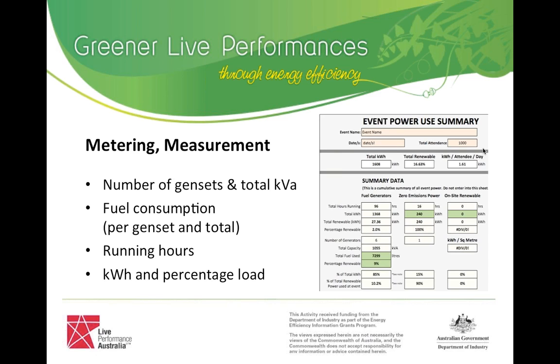Okay. So at the start, you there? Yes, hello? Yes. Yeah. At the start of an event, the kilowatt hour reading can be taken off the controllers on a number of machines. At the end of the event, the same can be, and you can work out your total kilowatt hours that way. We also have some logging functionality in the machines. We can actually log at set points in the machine. So every 5 minutes or every 15 minutes, we can actually see what loads on the machines.